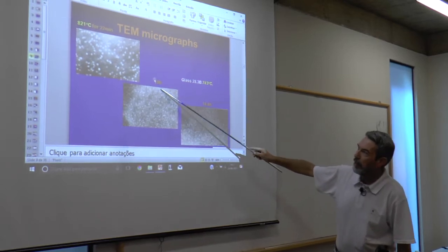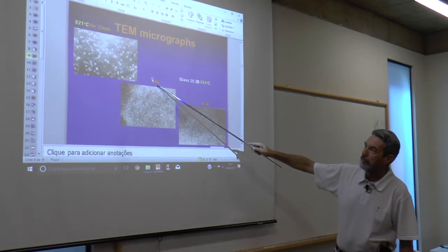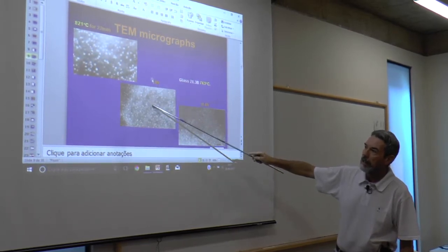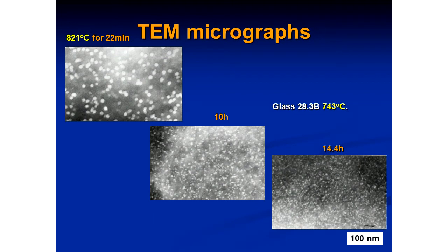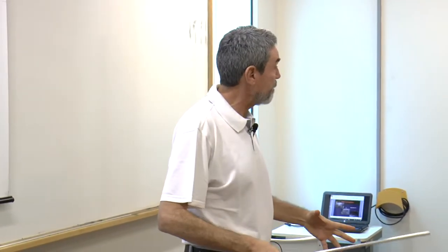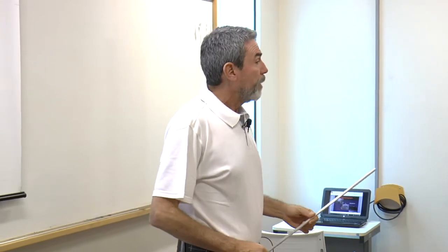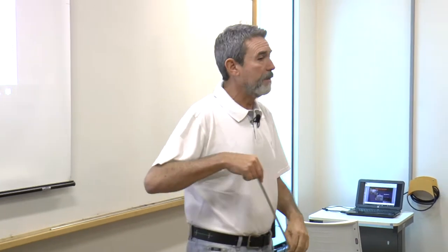Sometimes, you see, even a material which has not been treated yet already shows this phenomenon. In the cooling path, when you make the glass, sometimes it's very difficult to avoid the appearance of liquid phase separation because the kinetics is so fast. And you don't know. You think you are dealing with a one-phase glass and you are dealing with a 2 or 3 phase glass.